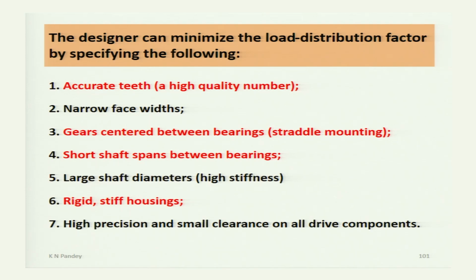The designer can minimize the load distribution factor by specifying the following: accurate teeth, a high quality number, narrow face width. We have seen that with the increase in face width, the mounting factor was increasing. So if the face width is smaller or narrower, then we can minimize the load distribution factor.